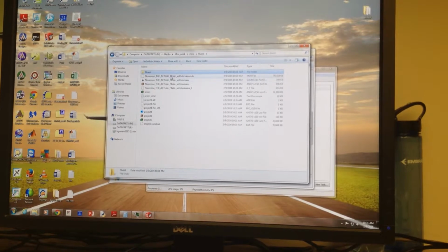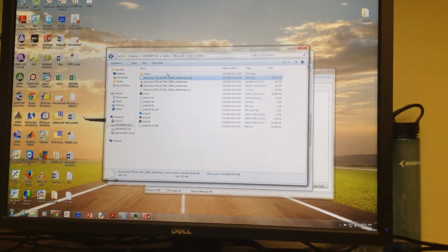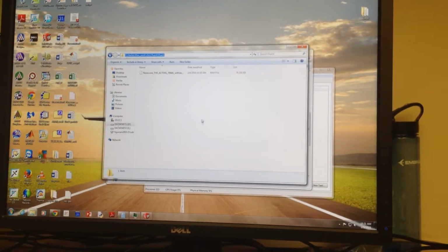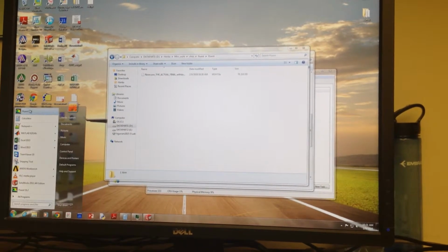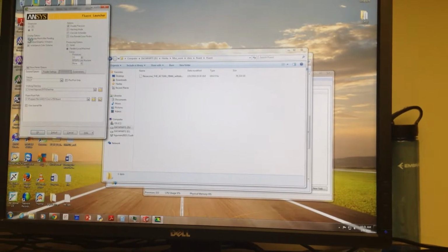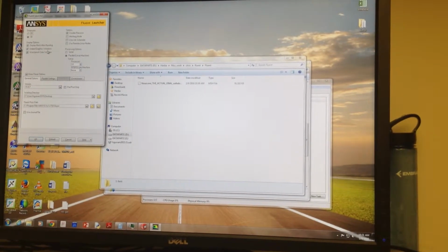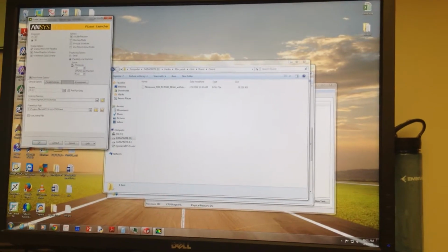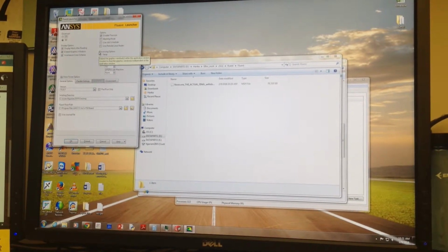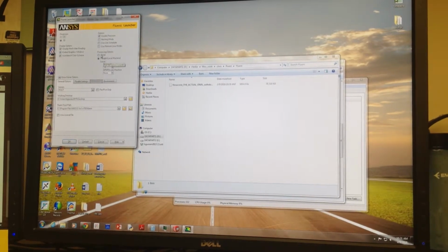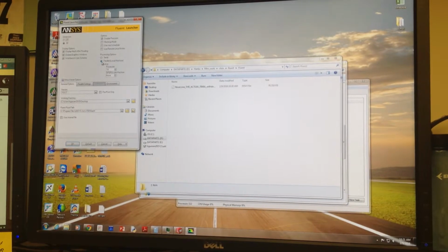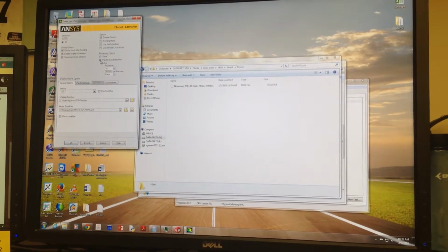Just click this. Put this in here. Copy, go, Fluent. 3D, double precision, display mesh after this. Graphic embedded windows, color scheme. Parallel or serial: you can use serial if you're using something on your laptop. If you're using a college computer or a school computer downstairs, you can just go for parallel.